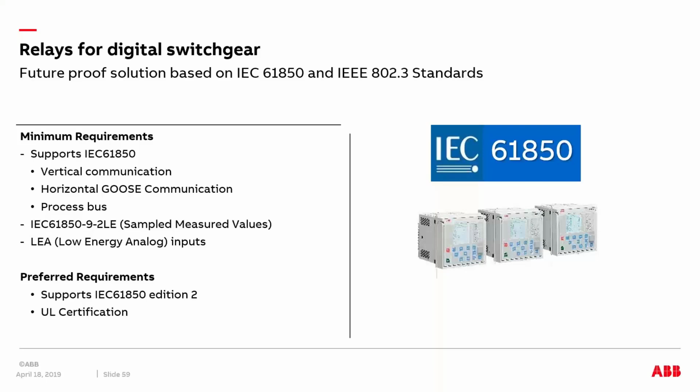And you need IEC 61850-9-2 LE sampled measured values for actually maximizing your benefits. And you need low energy analog inputs. So preferred requirements would be IEC 61850 Edition 2, which is the latest one, and UL certification.